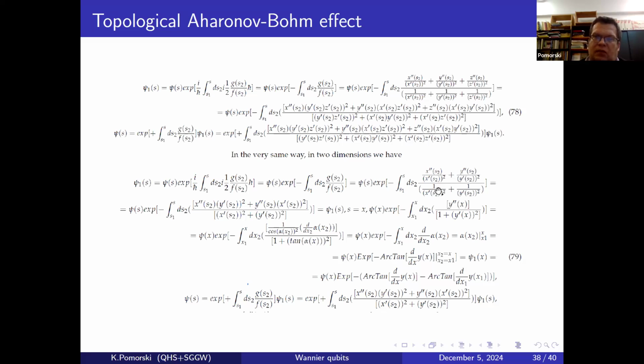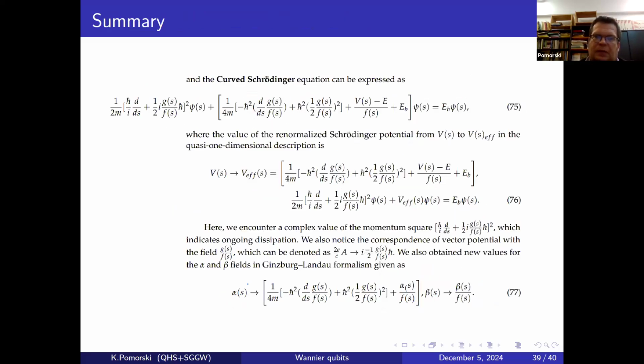So you have the banded nanowire in two dimensions, so you have x, y coordinates initially, and then that's just a question of some exercise to be done for somebody who's more interested. Yeah, so I have shown you this way of reducing a three-dimensional problem expressed in nanowires or in the chain of semiconductor quantum dots.